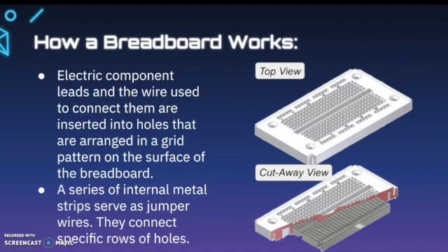So how does a breadboard work? Well, the electronic component leads and the wire used to connect them are inserted into the holes that are arranged in a grid pattern on the surface of the breadboard. You can see that in the top view. We have the top bar, as well as the bottom bar, and a series of rows identified by letters inside of that breadboard. Inside of the breadboard, a series of internal metal strips serve as jumper wires, and they connect